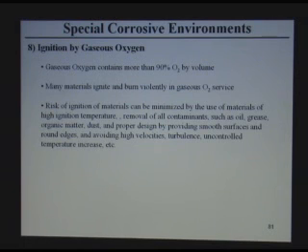You have to design properly to have smooth surfaces. You don't want to have friction. You have to avoid edges that cause turbulence. And you have to avoid high velocities, turbulence, and increases in temperature.